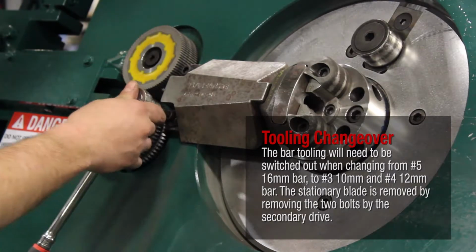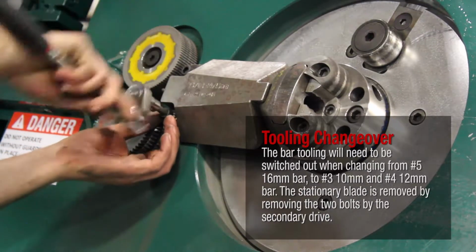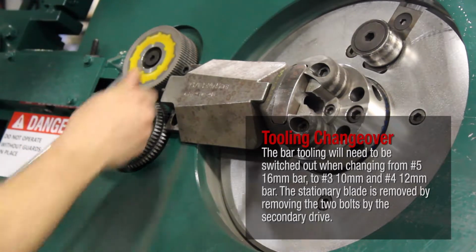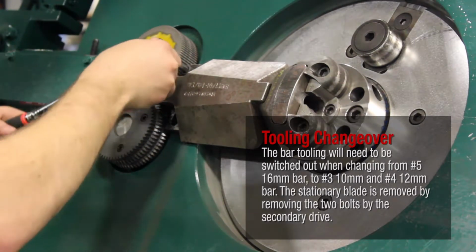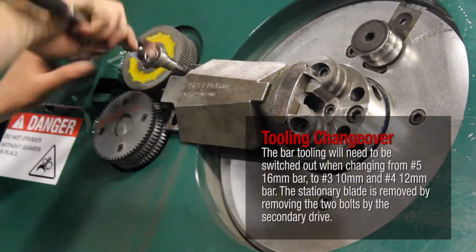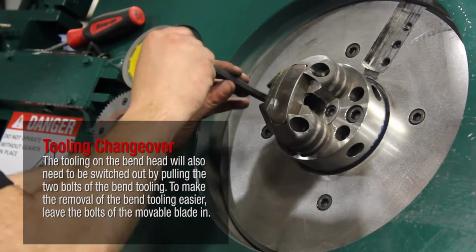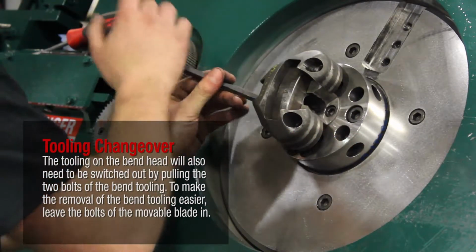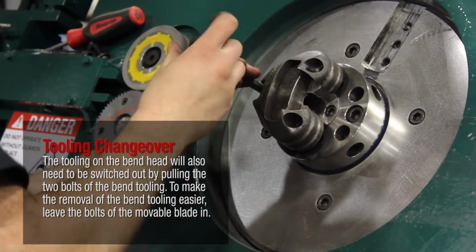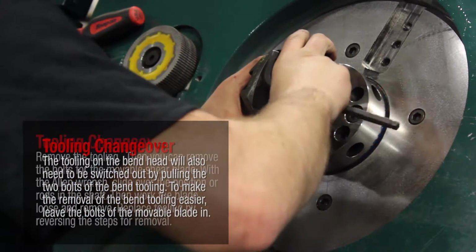Tooling Changeover. The bar tooling will need to be switched out when changing from number 5 16mm bar to number 3 10mm and number 4 12mm bar. The stationary blade is removed by removing the 2 bolts by the secondary drive. The tooling on the bend head will also need to be switched out by pulling the 2 bolts of the bend tooling. To make the removal of the bend tooling easier, leave the bolts of the movable blade in.